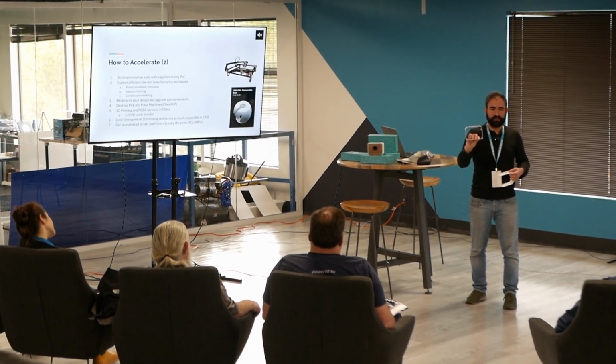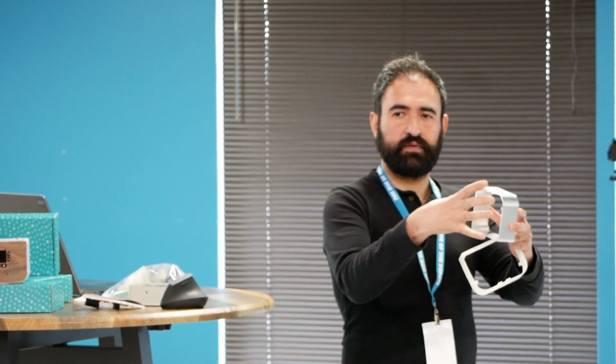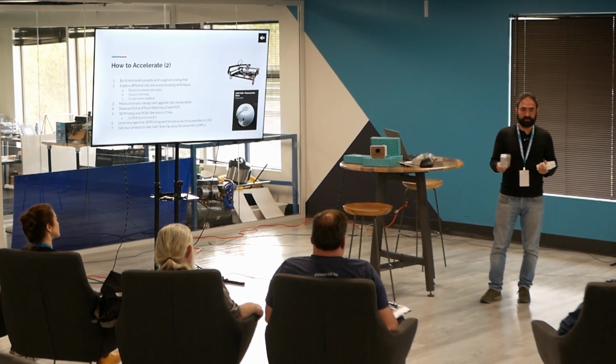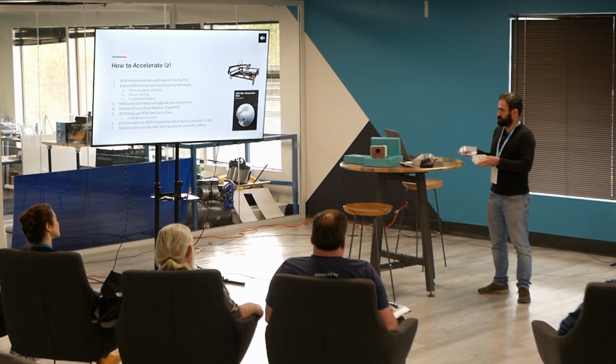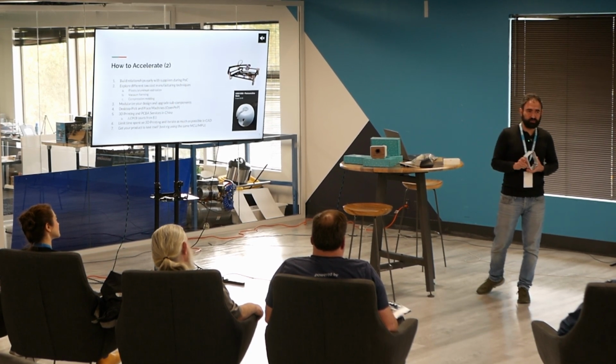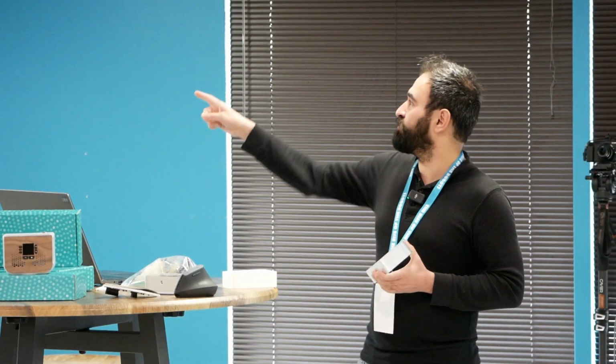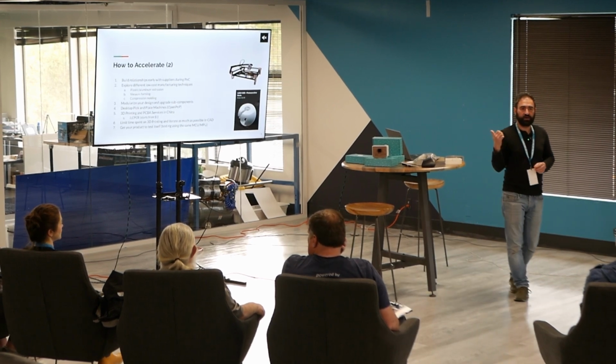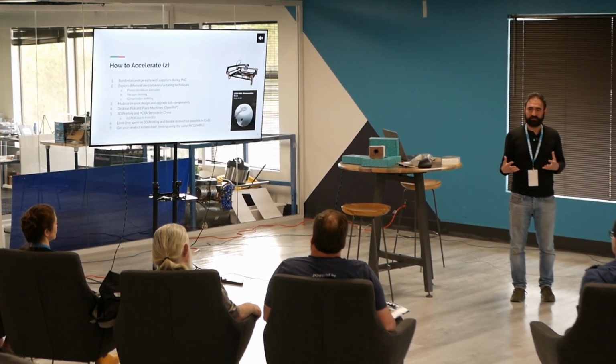And extrusion is very cheap compared to other ways of making the product. This thing will come out of the extrusion die like a bar, and it gets cut into pieces, and then they will machine it, post-process it on a CNC machine. You can extrude plastic, you can extrude many different kinds of material, and it costs $1,000 to make an extrusion die, or even less than that. All the frames in the office here, you see, they made custom extrusion profiles for them, just for connecting these frames of offices.